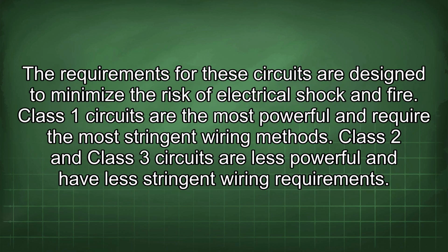The requirements for these circuits are designed to minimize the risk of electrical shock and fire. Class 1 circuits are the most powerful and require the most stringent wiring methods. Class 2 and Class 3 circuits are less powerful and have less stringent wiring requirements.